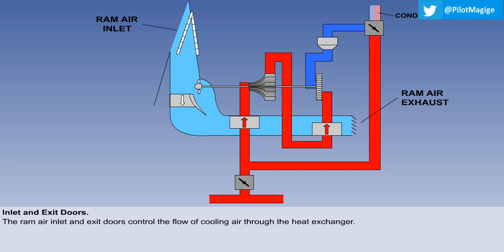After takeoff, once the flaps are retracted, the doors will modulate as required to maintain the required pack outlet temperature. In some systems, they are automatically closed during takeoff and landing, to prevent debris damaging the system components.